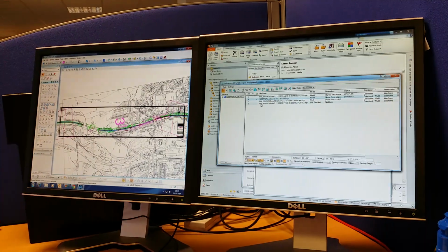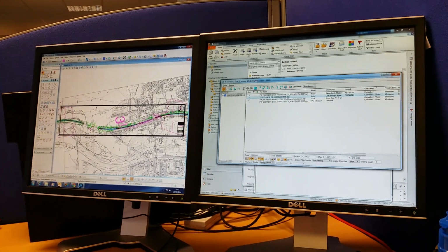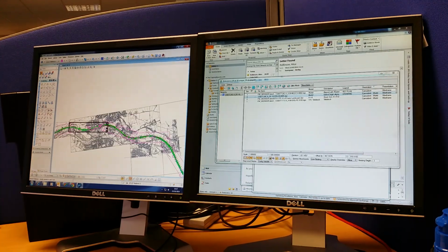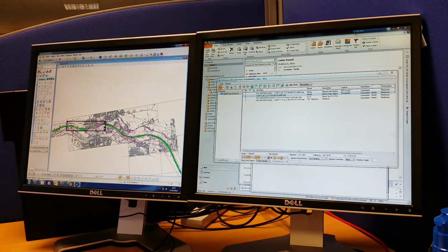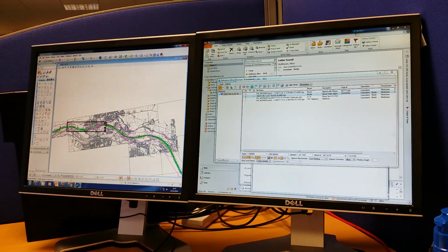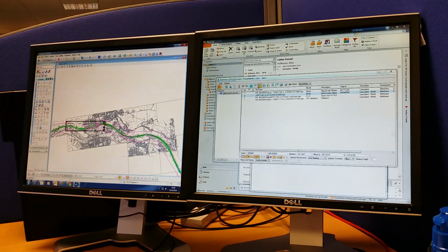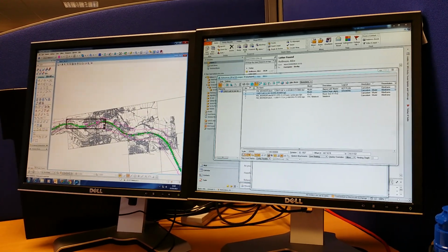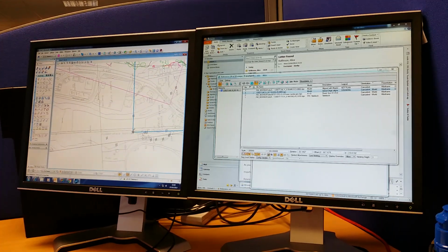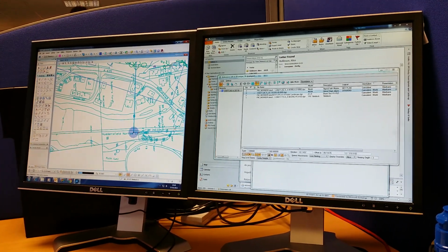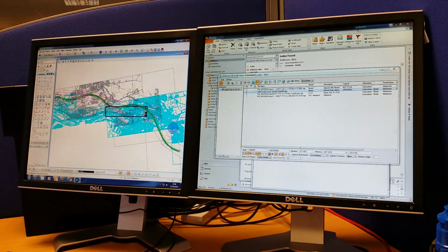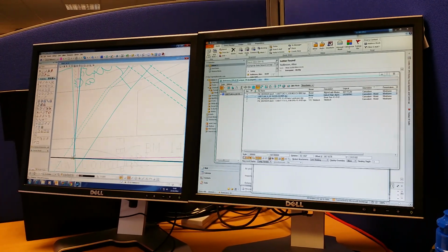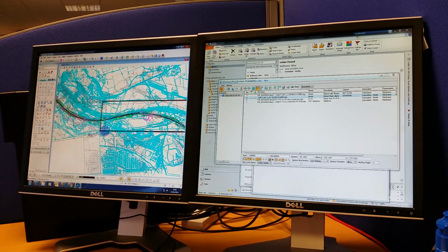And then what we do is, you say this is sheet 5. So, you need to put sheet 5, which obviously is here, over sheet 3. So, select, move the reference, pick the bottom corner of the sheet outline and move it to sheet 1.